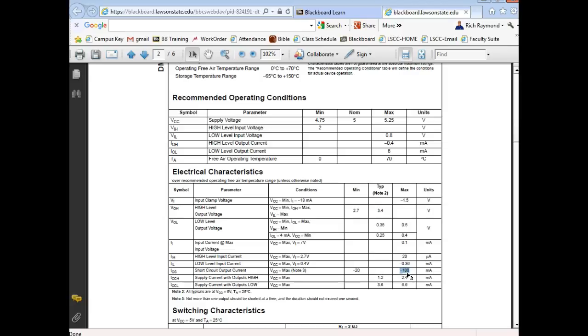That's if you short out the output, if you short it to ground, or common. And you can do it, and it won't hurt the gate for a while, but you don't want to do it real long. It really comes into play when we deal with trying to set up a tied AND or a tied OR, right? You understand?